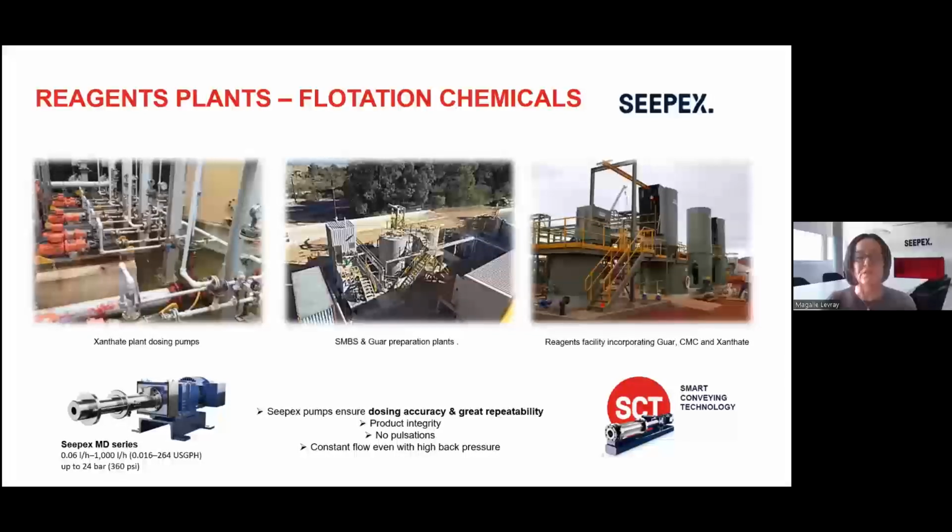So very often I can see peristaltic pumps used on this application as well, but just above 3 to 4 bar, the dosing accuracy isn't that great. Whereas with a progressive cavity pump, the dosing accuracy will remain perfect even with pressure variation.